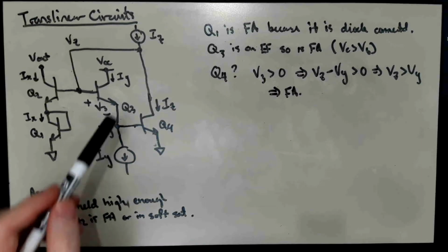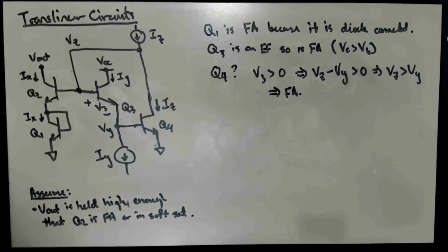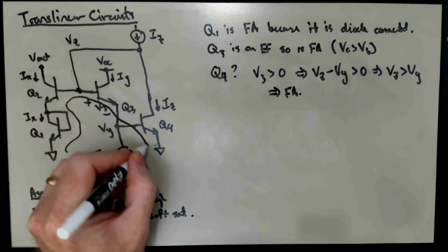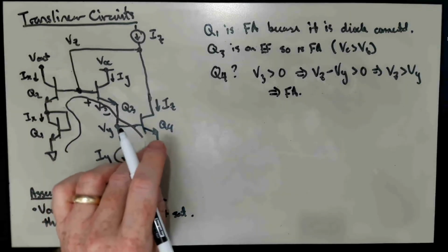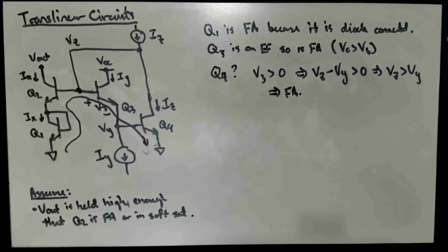Okay, it's actually a whole diode drop, or 1 VBE, into the forward active mode beyond a diode connected transistor, which is just on the borderline. So, yay verily, all 3 devices are in the forward active mode. We still have the same translinear loop, because we really haven't changed the circuit at all, other than by flipping that diode connection around and changing what we're calling the input and what we're calling the output.